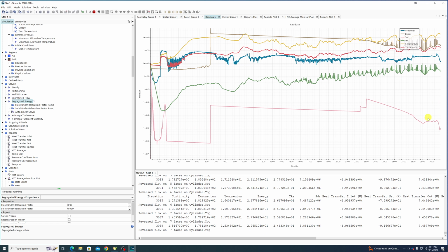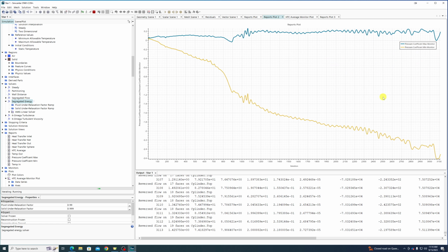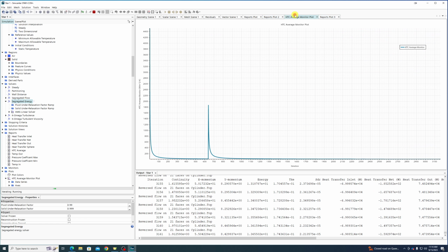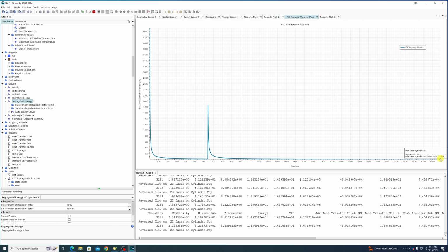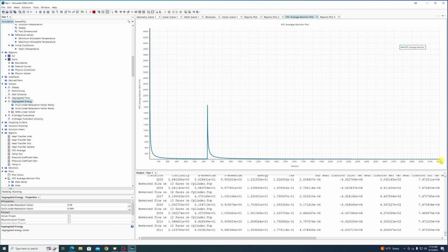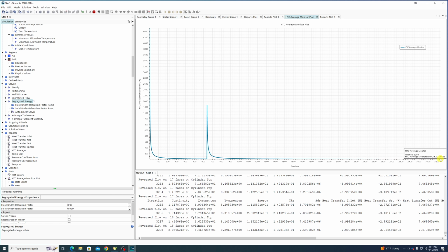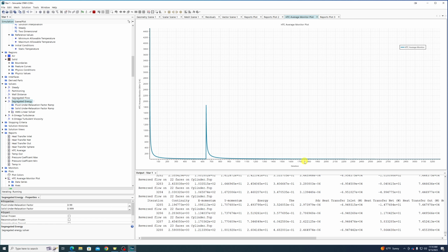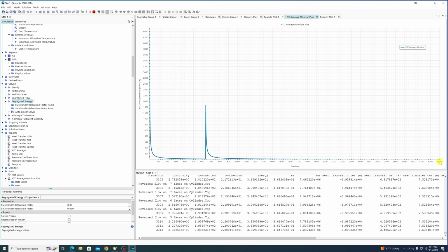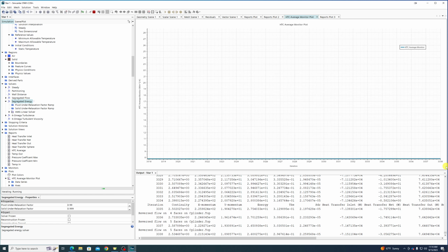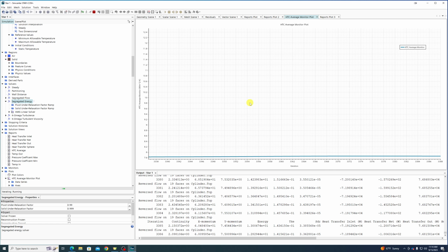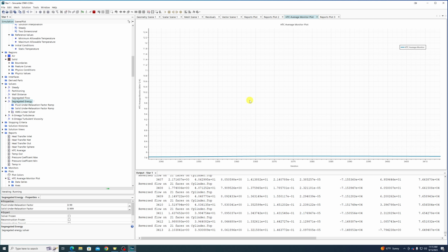But you can indeed notice some amount of stability by looking at temperatures, by looking at the heat transfer, by looking at heat transfer coefficients, which this one is natural convection. It looks like it's about 8 is pretty much what this HTC is converging at. Thereabouts. It's oscillating a little bit.